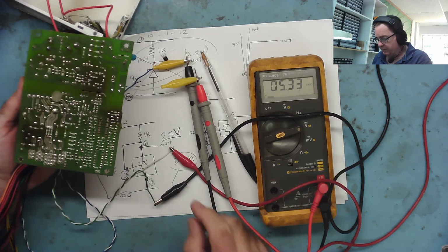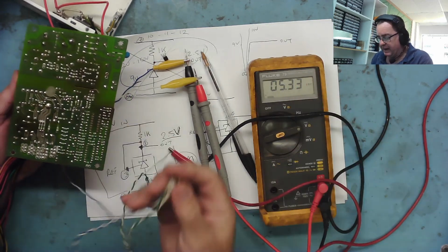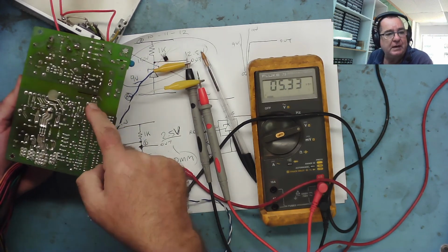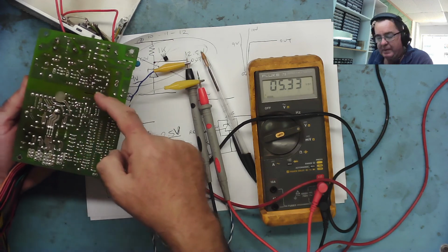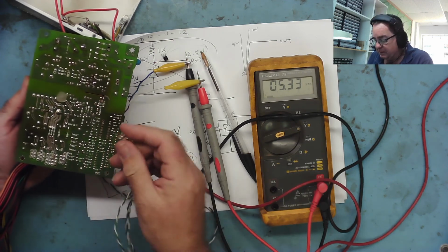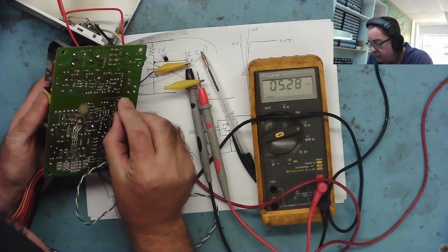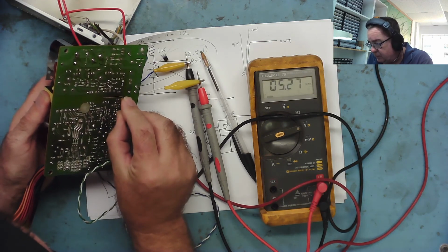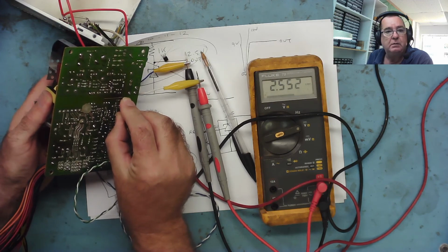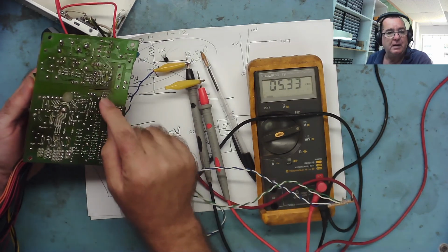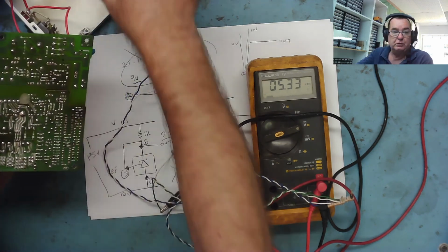Okay. Zoomed in a little bit, so it's all connected up. So this is our little tester. The 431 is actually here. This is the opto-isolator across the big divide between the hot side and the cold side, high voltage and low voltage. Let's see if we can connect this onto here, so we get a good connection with it. Yeah, look, there you go, 2.55. So I'm now testing them in circuit as well, and that worked okay. So we know that's a good one.